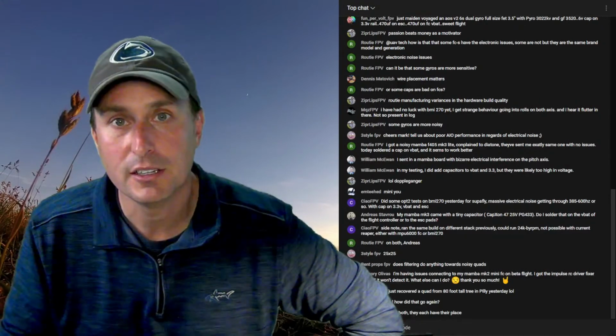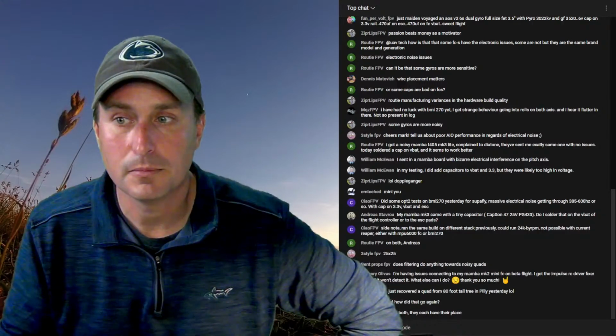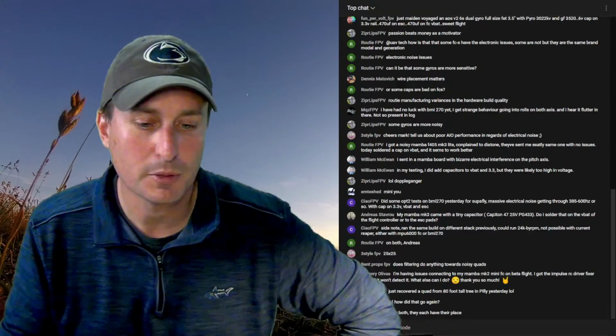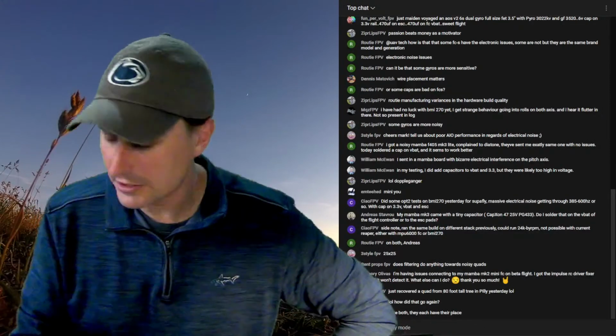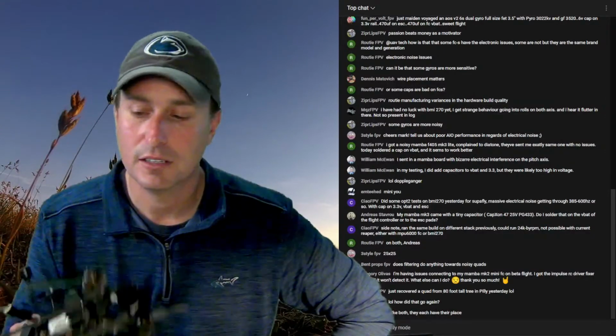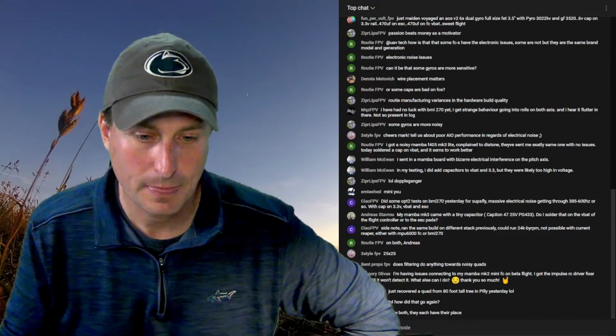I know Brian White does a lot of cinelifter tuning, so he has a lot of experience, and same thing, put a cap on VBAT. Basically, the bigger the motors, the more capacitance you will need, because they give more back EMF, electrical noise.